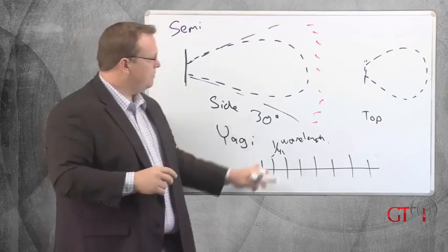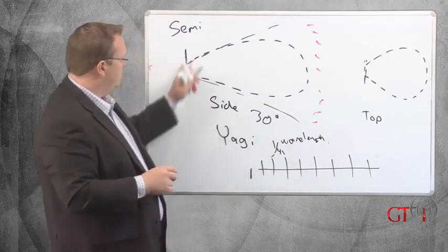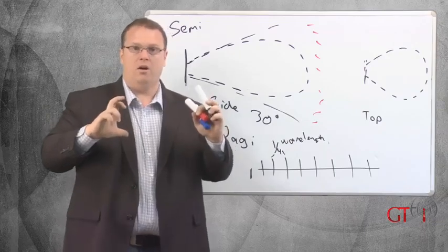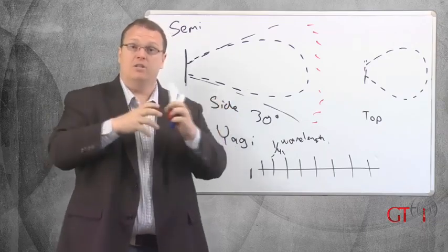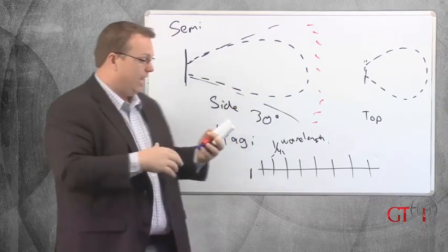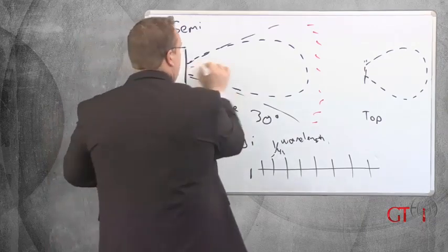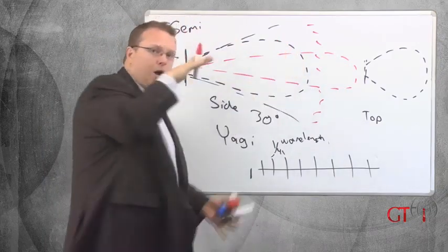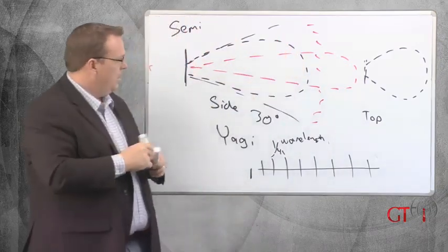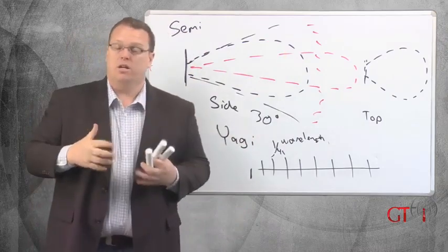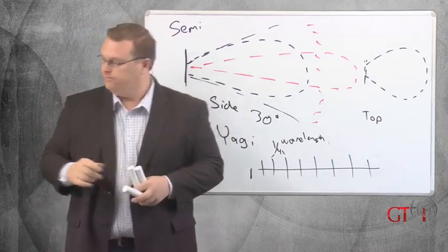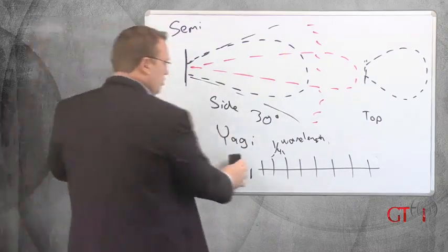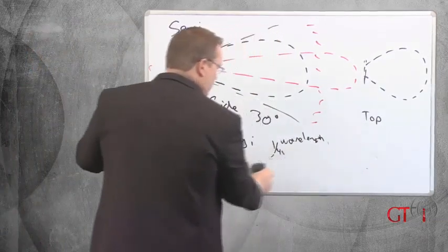So these are different types of semi-directional antennas. You'll see them physically, a lot of times they're square, different sizes for different gains. Larger antennas always have higher gains. Remember, a higher gain equals a lower beam width, so we can go farther, but we're compromising because we're squishing that dough. So these semi-directional antennas definitely have their use. But then we move into highly directional antennas.